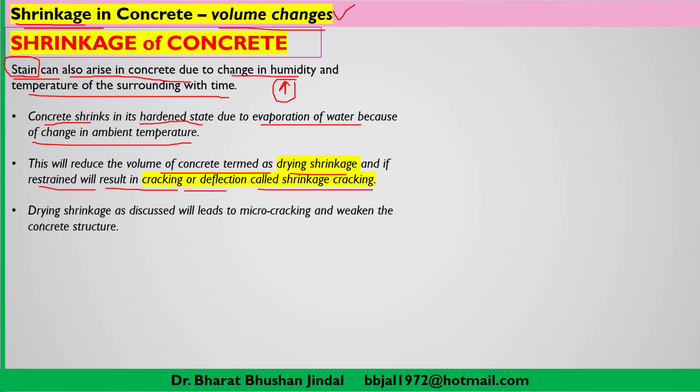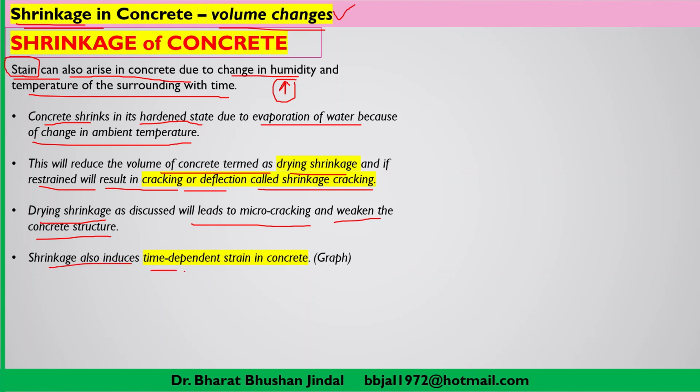Drying shrinkage, as we have discussed, will lead to micro cracks. And when the concrete structure is prone to micro cracks, or some cracks are emerging in the concrete member due to evaporation of water, it will definitely influence the strength of the concrete. That means it will weaken the concrete structure. Shrinkage also induces time-dependent strain. Let us go through the graph.